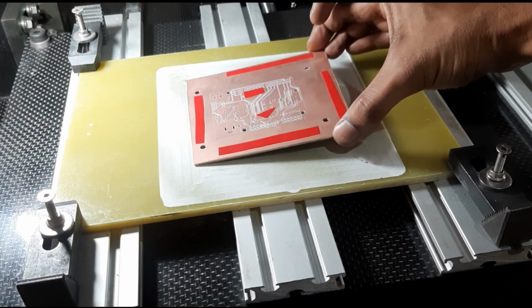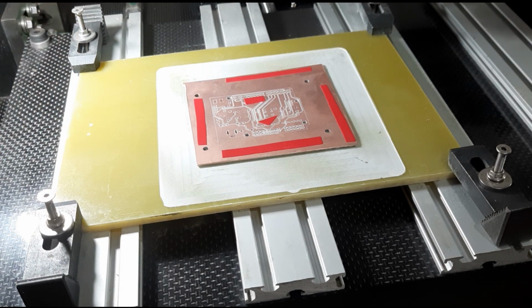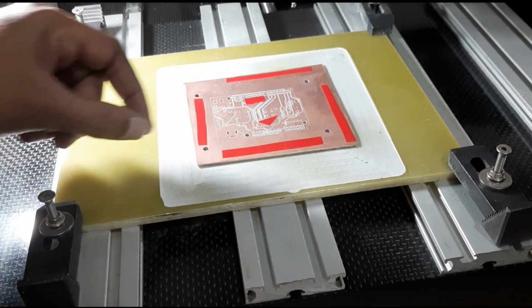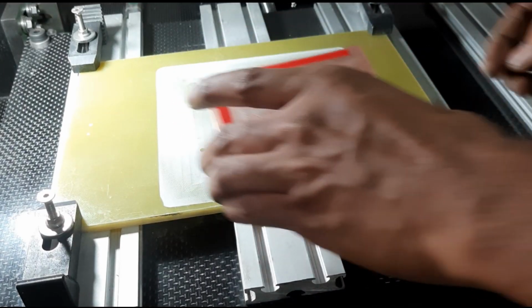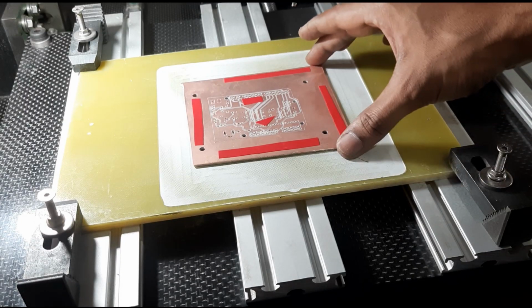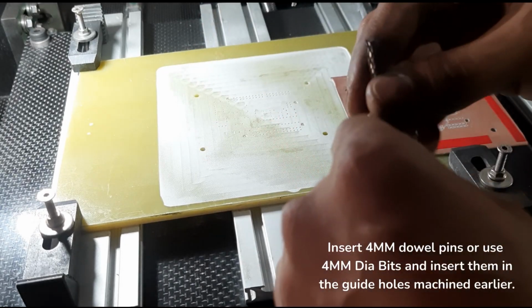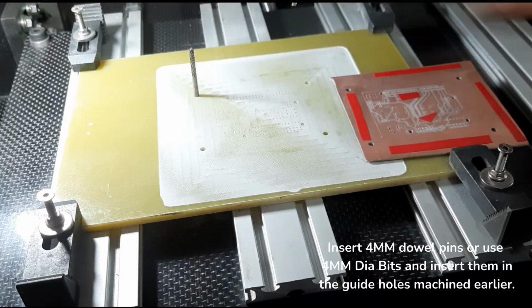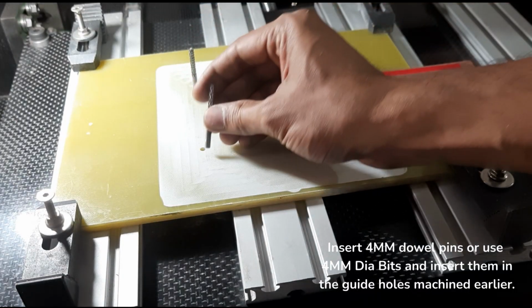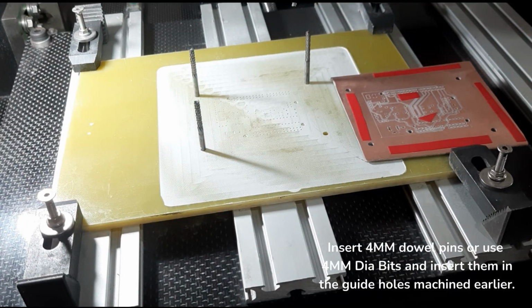Now that we're done with the top side, we have to flip it. So just like we did when we were milling the top, we have to stick the PCB board to the waste board. I'm going to put 4 small strips of double-sided tape again and small bits in the center so that it doesn't bend. Then we can insert double pins into the alignment holes that we created earlier, and slide the PCB board along those alignment holes so that they are perfectly aligned and flipped. Take care that you flip it along the x-axis, because that's what we have defined, and also ensure that you're flipping the correct side.